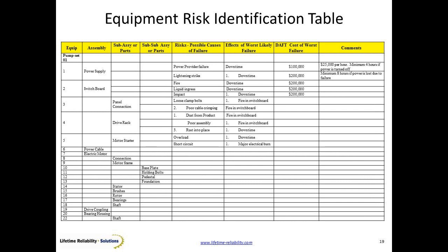So in the end, we're going to build a table. It ends up being a documented process. I'm going to have my asset broken down by its assemblies, and necessarily perhaps even its parts. Each of these parts will have its different possible causes of failure from that list and from the brainstorming. I don't mind. I'm just looking for stress. Whatever can cause a stress, I've got to find that cause.